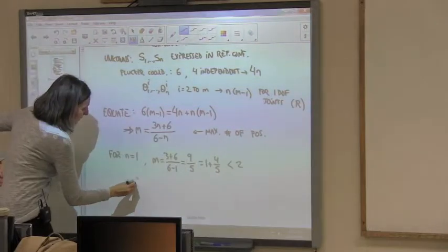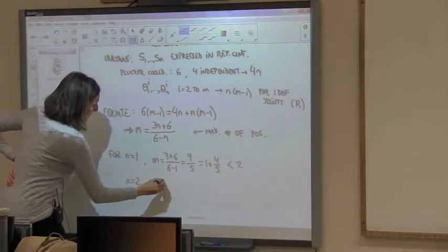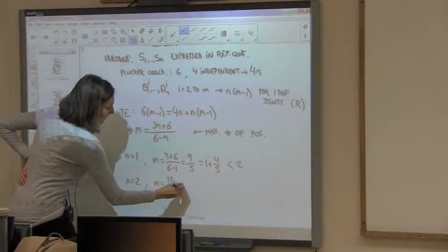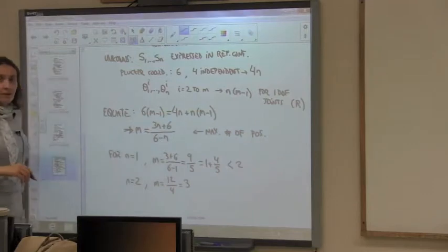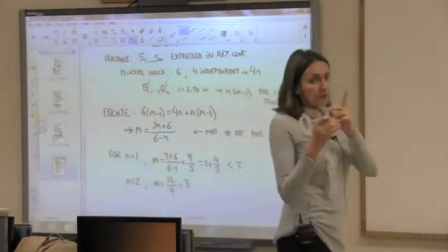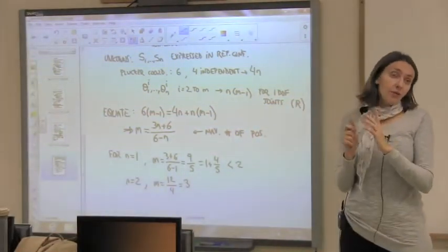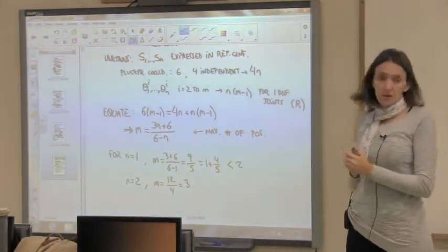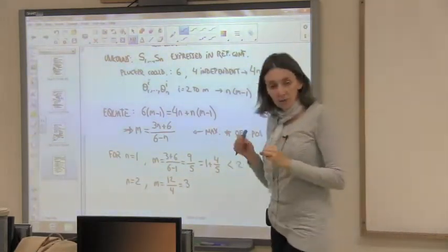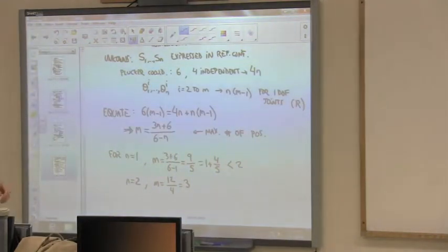A single revolute joint won't be able to solve this. N equal 2, this is the RR serial robot. M equals (6 plus 6), 12 divided by 4, and this is 3. That means a serial robot with 2 arbitrarily located revolute joints can pass exactly through up to 3 positions, no more. If you define a 4th one, you can make it go close if you want, but it cannot fully reach that position if it's an arbitrary position.